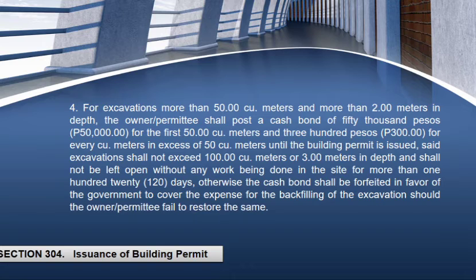Said excavations shall not exceed 100 cubic meters or 3 meters in depth and shall not be left open without any work being done in the site for more than 120 days. Otherwise, the cash bond shall be forfeited in favor of the government to cover the expense for the backfilling of the excavation should the owner or permittee fail to restore the same.